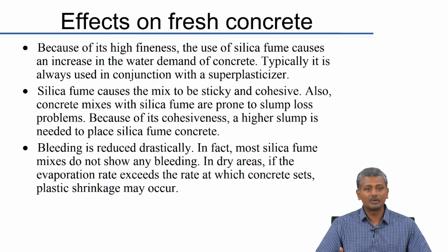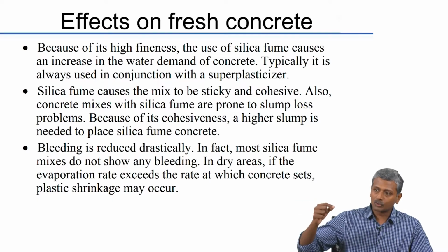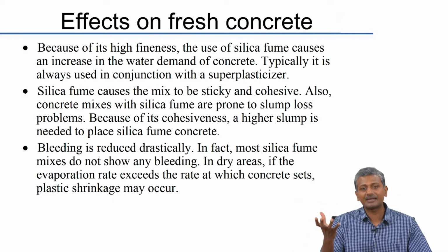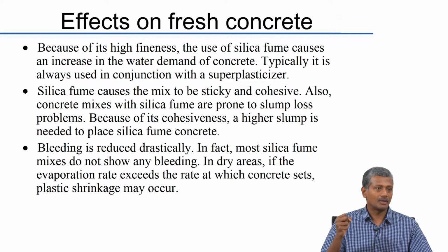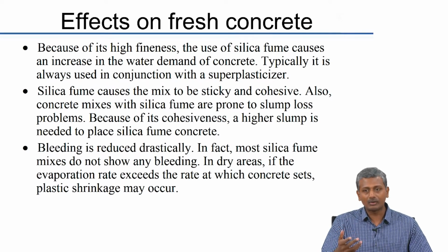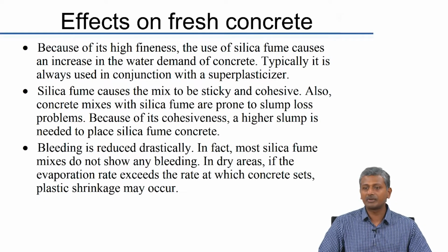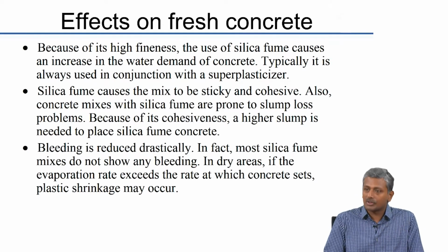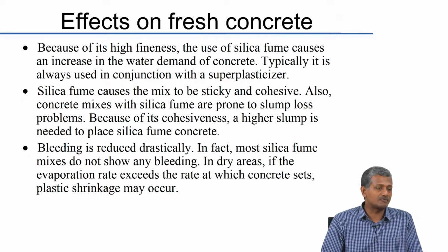Or if you are making a grout for a post-tension application, right, where your grout has to actually flow through very small constricted spaces without getting segregated, the silica fume particles do very well in actually reducing the segregation. Okay. But the problem with that is felt in the regular concrete construction. When you do a regular concrete construction, if your mix becomes highly cohesive and sticky, compaction and finishing become a difficult task, especially finishing. Okay. So, that is one major issue, and the other aspect is that your slump loss is also large, because a lot of the water gets lost in adsorbing on the surface of these extremely fine particles.